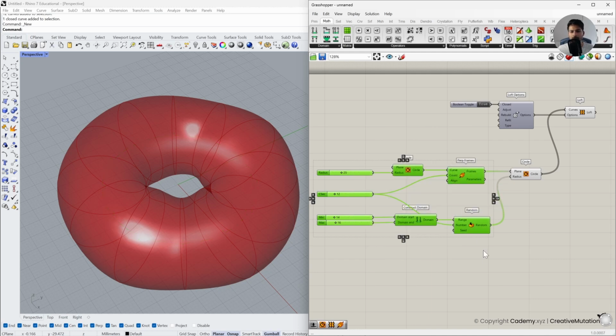It's really important in Grasshopper that you keep on disabling the preview of the previous components, as generally you will be modeling one geometry on top of another geometry. It's important that you hide the previous geometries, or else you will get confused. All right, so you can select the components, middle mouse button, enable the preview, or middle mouse button, disable the preview.